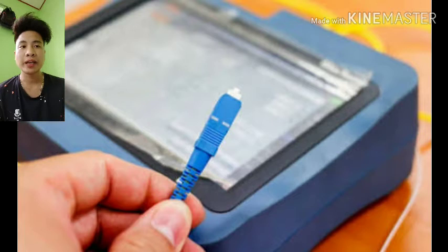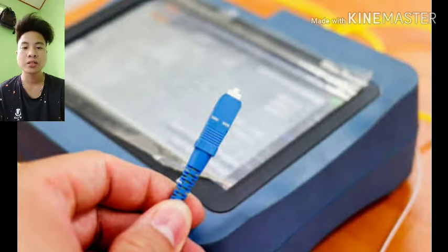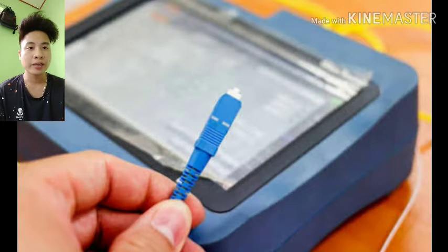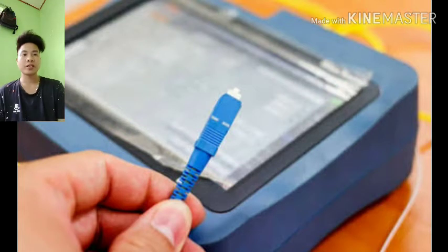Testing fiber cables. We have a misalignment: the fiber optic media are not precisely aligned to one another when joined. And second, end gap: the media does not completely touch at the splice or connection. So third, end finish: the end of the media is not well polished or dirt is present at the termination.